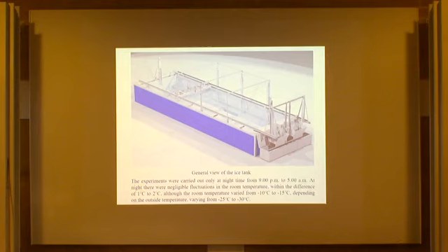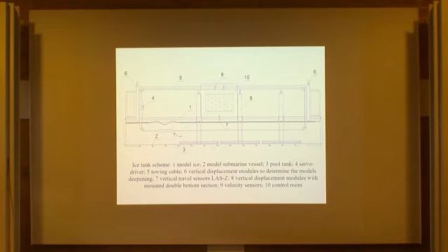To conduct the experiments, the necessary equipment and measuring systems to register vibrations of model ice were prepared. By towing the model vessels with velocity, the profiles of flexural gravity waves were determined. To record the vibrations of the model ice, we used infrared non-contact vertical displacement sensors. The profile of the waves generated by the moving model was recorded with the help of the program Test Viewer.